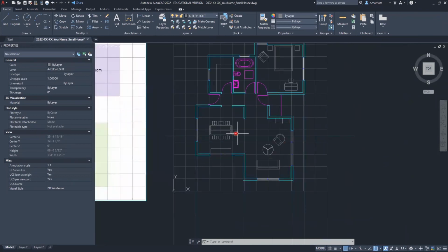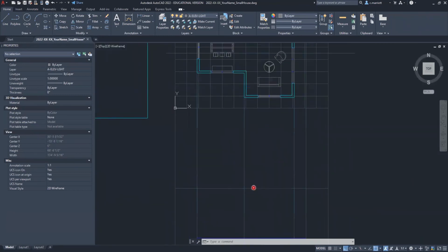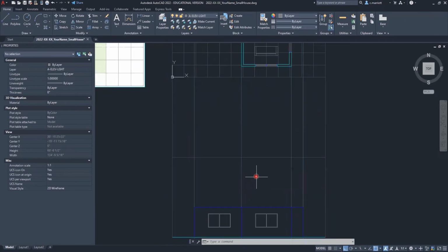And one thing that I would always recommend when doing a section is, before you draw all the stuff in the background, like these doors that are going to show in my section, I would always draw whatever I'm cutting through in this cutting plane. So that's going to be the ground, floor that runs along here, the ceiling, and these walls with their windows in them.